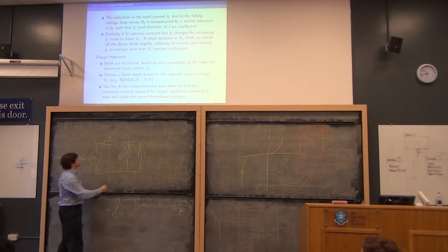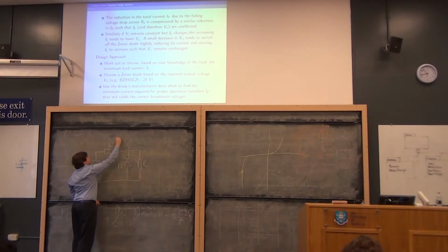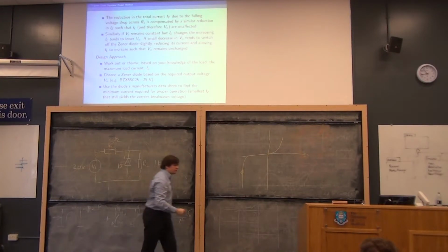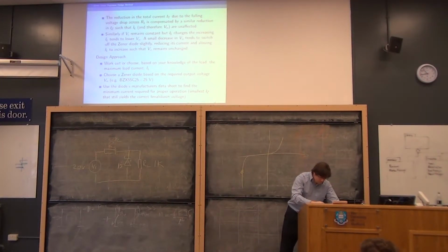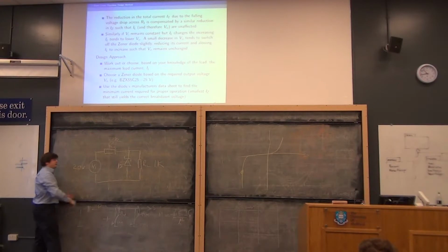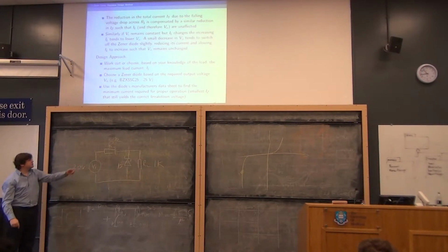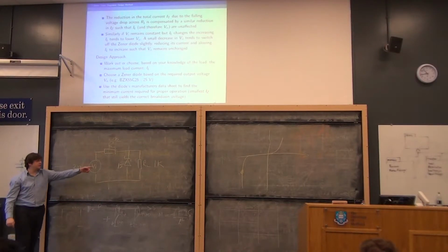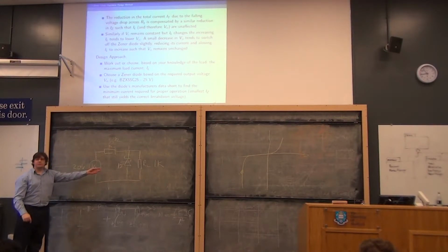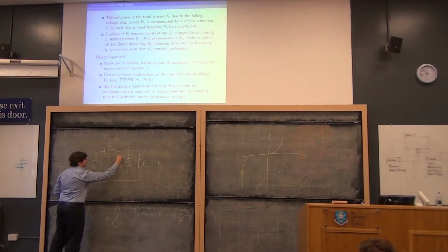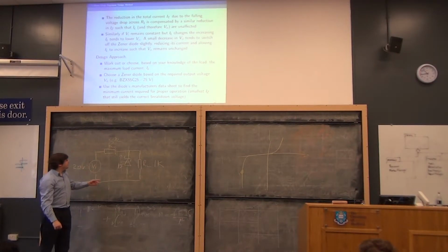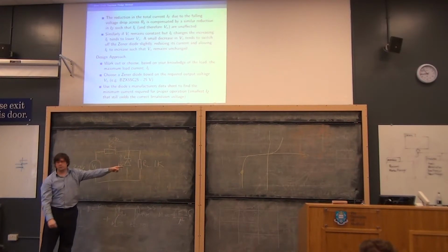And if I was to say, for the sake of argument, this is 10 ohms, and this is maybe 1 kilo ohm. We'd say, all right, well, this is going to be very, very nearly 20 volts because the ratio of those is 1%. So this will be 19.9 volts across there, more or less. In that case, it's more than 15, so the diode breaks down and conducts some current. How much current will it conduct? Well, it depends on the value of RS and the slope of that graph.